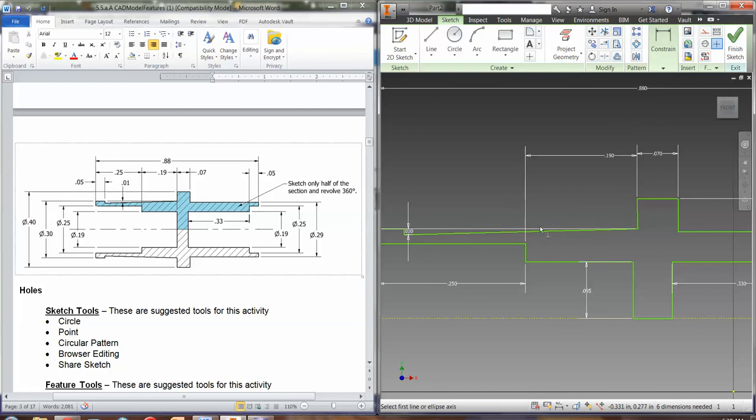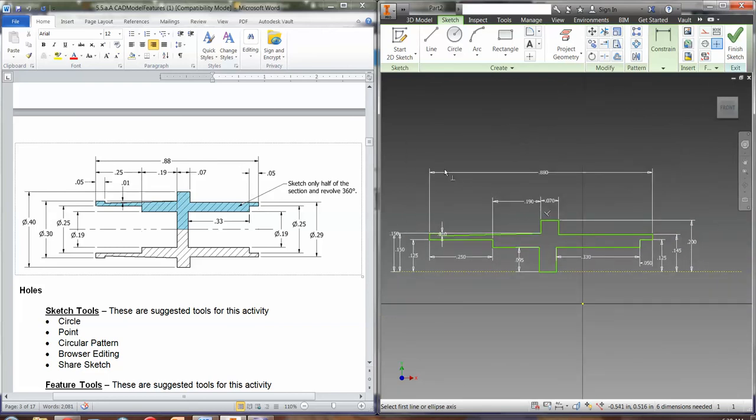So what we're going to do is I'm going to delete this line here. That's where we have a perpendicular there. That's our problem. So we can see we have an additional constraint there. Delete that constraint. Try and put the perpendicular up at the top, because that's where it actually needs to be. Now it's straightened it out. Good. So that was a hidden constraint that we put in unintentionally. And now we're done with this sketch. We have all of our bits and pieces.